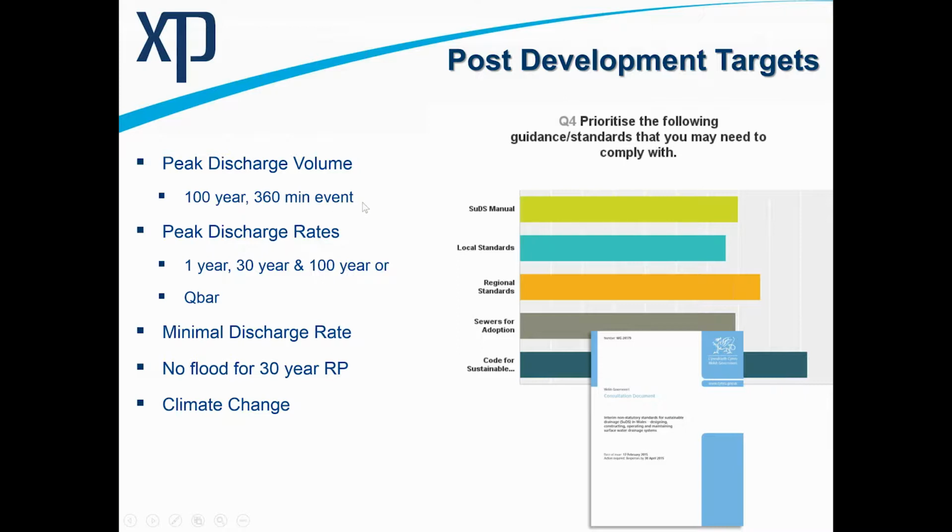If the volume that we generate post-development is greater than the Greenfield volume, then we'll be limited to one discharge rate, and that will be the Q bar figure. So this is the kind of thing that will happen when we're in clay soils. We'll typically be limited to the Q bar figure, and then the additional volume that we're generating will need to be managed on the surface.